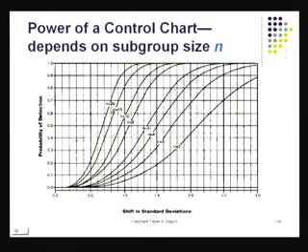This by far, what I am discussing, is probably the most complex part of control chart theory. So if you do not understand this completely, do not worry about it, but keep your N near 4, 5, 6 and let at least a sizable production take place, which could be like after an hour or after maybe a shift or something like that, to collect the next sample.